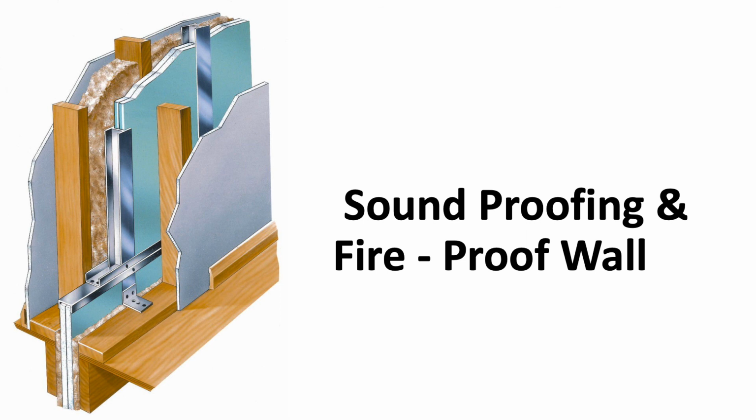Most hotels on the party wall, being the wall that separates one room from the other, will have a layer of sheetrock and a layer of plywood that the sheetrock's attached to. Then they'll have a 6-inch party wall in between them, full of insulation. Then on the other side, you've got another layer of plywood and another layer of sheetrock. Now, if you're not drilling holes into that wall and inspecting what you've got inside the wall, the chances of getting the wood and stuff inside that wall dry through a layer of 5/8 sheetrock and a layer of 3/4-inch plywood,